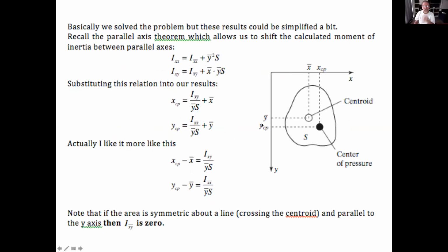Okay, so now this looks a bit complicated. So hopefully we can simplify it. And this page actually shows how to make things much easier to work with. I already established a simple system to generate the force: figure out the centroid, figure out how deep the centroid is, get the pressure at that depth, and multiply by the area to get the force. Hopefully we can do something very similar in order to calculate the center of pressure.